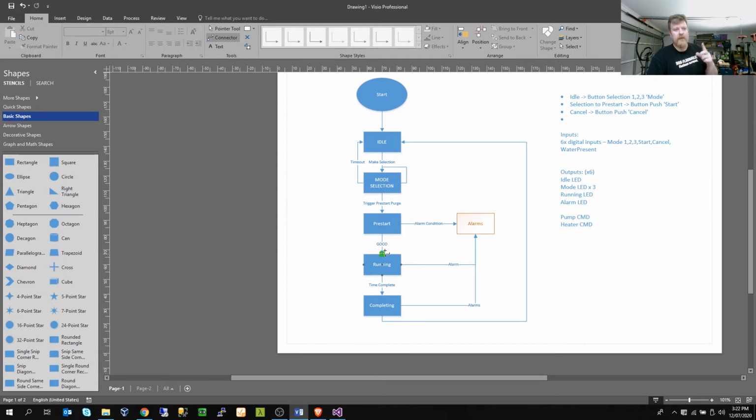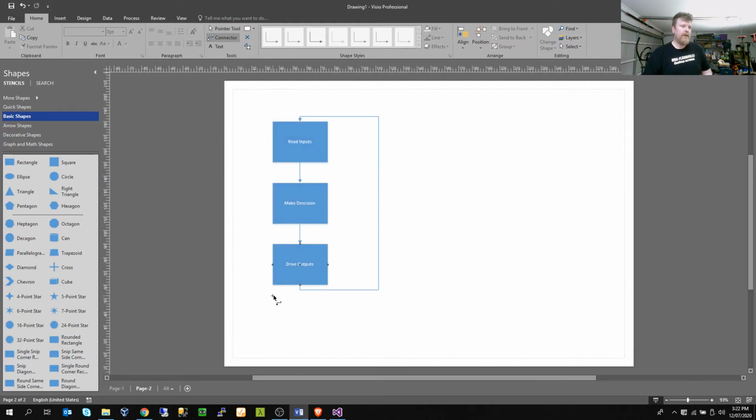We're not really good at doing that math on the fly, and we make mistakes, we make misinterpretations, and in the middle of the night when it's freezing cold and you're knee deep in mud out in the field somewhere in an industrial process, A, you don't want to be making mistakes, and B, you want this to be as easy as possible to diagnose. So scale your analog values. It will make a big difference, and maybe not to you, but the person that follows you will certainly be pretty happy about it. So I would lay my program out somewhat like this.